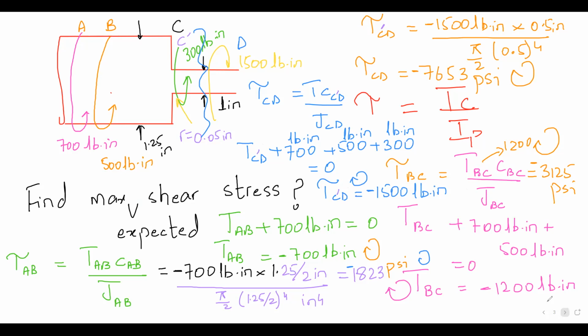Last semester as well, when I was going through this problem, I stopped at exactly this point. I don't think this is clear. For this kind of question, we need to look at the dimension changing part, because this part answers our question. What is the biggest stress? Stress concentration. Stress concentration will happen where you have a sudden change in the size. So this is the point of concentration. All of us try to squeeze through this door. This is the limiting portion; the value cannot exceed the maximum one.